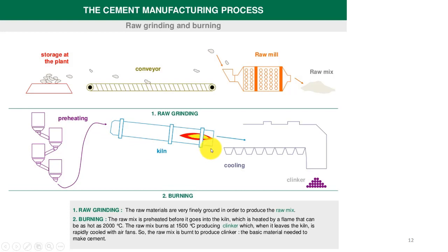After the clinker is formed, the clinker is subjected to a fairly cool environment by convection, so that the clinker can be cooled down. When the clinker has cooled, it is ground to a finer particle size, so that the cement particle size is between 2 and 50 microns. The minimum particle size would be around 2 micrometers, and the maximum must not exceed 50 micrometers.